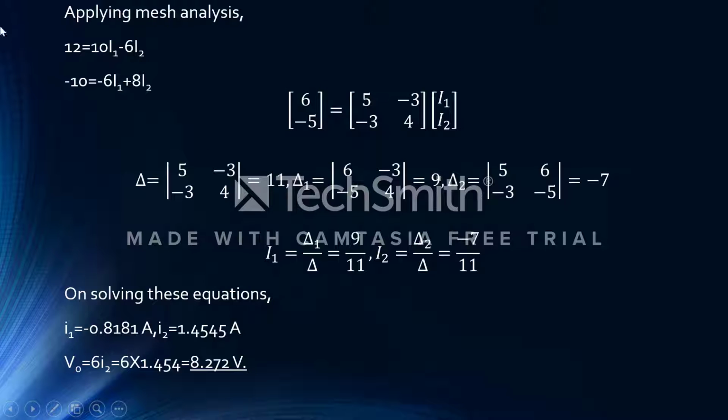We are first going to simplify these equations. On dividing by 2, we get 6 = 5I1 - 3I2, and dividing the second by 2 as well, we get -5 = -3I1 + 4I2. We are going to write this in the form of matrices. So here is the way we represent the equations in matrix form.